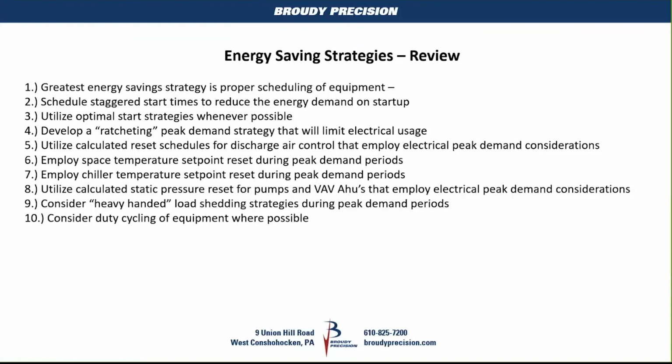One of the things that I do for static pressure control, and that would be either for pumps or for, say, VAV air handlers, is you could reset your static pressure set point. Instead of maintaining 1.5 inches on a VAV air handler, if we get into a high demand situation, maybe we lower that number because we're in a peak demand situation. And we want to reduce the amount of energy by slowing the speed of the fan down.